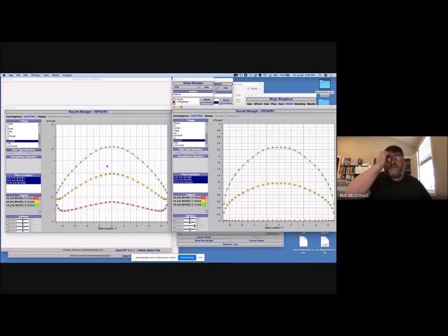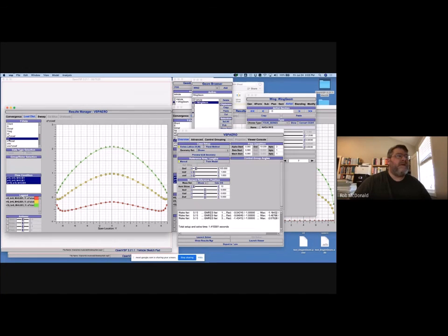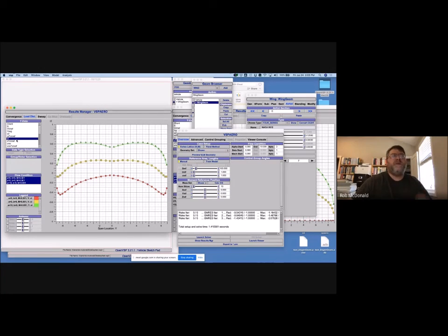When we're interested in stall from a lift distribution standpoint, we probably want to look at this chart, the little CL. So not multiplied by chord, but just the little CL. So that's the local lift coefficient. This is basically how hard we're working each section, and what we want to watch for is how high these sections get. If we're using an airfoil that stalled at, let's just say, a local CL of 0.6, then we would look at this kind of distribution and say, I expect the wing to have stalled from about, we'll call it 20% to 60 or 75% chord, right? In this region, we expect it to have stalled, but out here at the tip, it has not stalled, right? So we can look at the CL distribution.